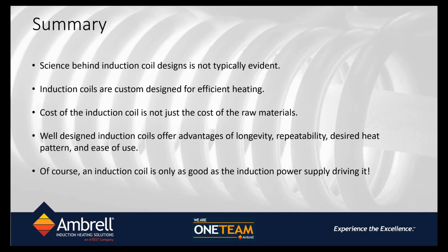All right, thank you. Our next question here is, how does coil part inductance change when materials change? For example, if trying to use a coil designed for steel to heat aluminum instead, and vice versa. Great question. Our experience has shown that when you put an aluminum part inside the induction heating coil, the inductance of that whole setup actually goes down. So the frequency goes up.